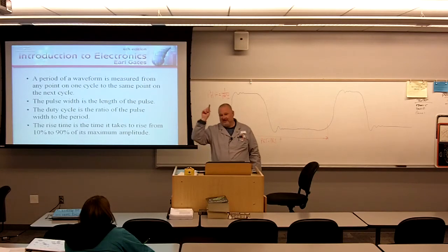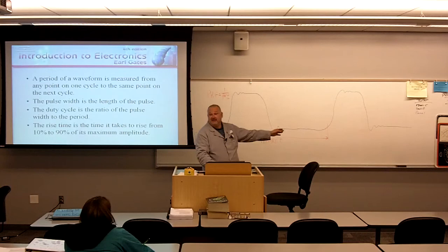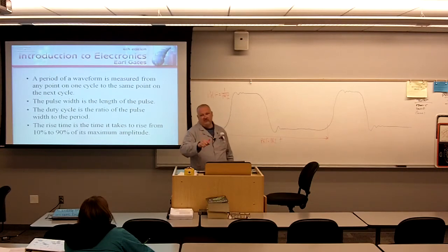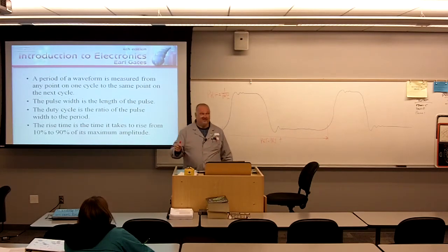And the reason that I was using a calculator, I had on a computer screen what the computer thought the PRF was, but I didn't trust the computer. If you trusted the computer, you might kill a friendly. And I didn't want to trust it. I wanted to look at it, because if I'm looking at this, there's no way of faking it. If I perform that pulse repetition interval measurement and calculate the PRF, then I could check my computer and make sure my computer's not giving me bum dope. Because the military, it's like life or death, so you can't make mistakes with that.